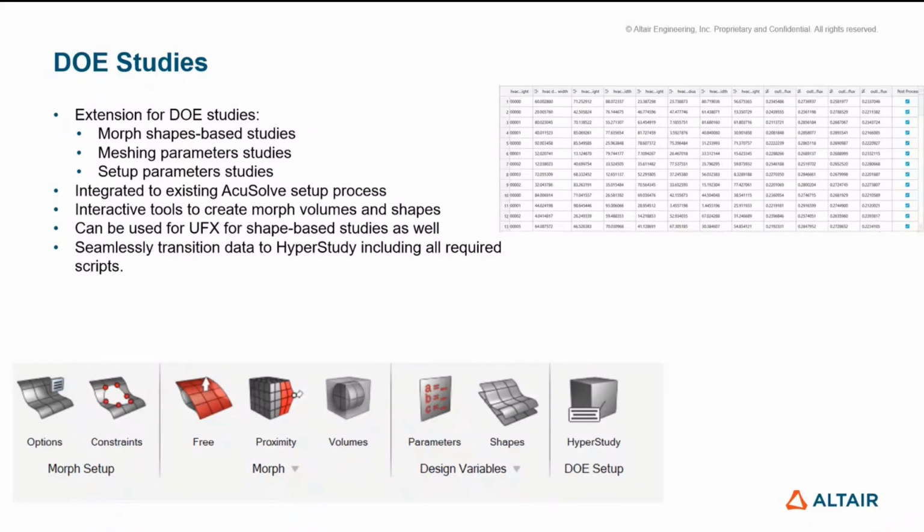It is integrated with the existing AccuSolve setup process, and we have added interactive tools to create the morph volumes and create the shapes. And this can be utilized for UFX as well, to perform the morphing and run the DOE studies. And it also passes the data to HyperStudy, so you can perform all the studies in HyperStudy.